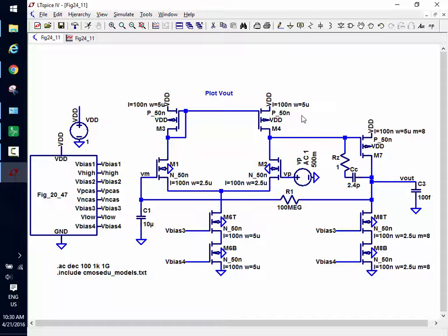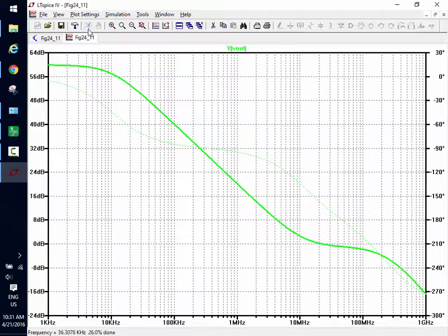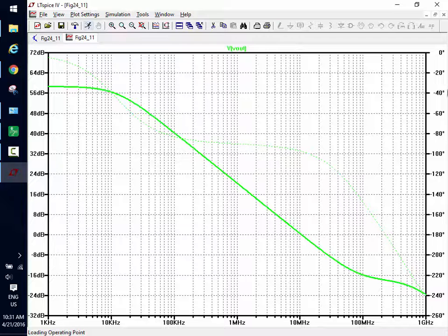So all of these changing the width and stuff, you can do it on your second stage, right? Well, no, you can change the width of your diff pair a modest amount because that'll increase the GM. So if you want to push your unity gain frequency out a little bit, you can do that. Is everybody cool with this? So let's see what happens. Notice how the pole moved out, moves the 0, too, but notice how it's more stable now.